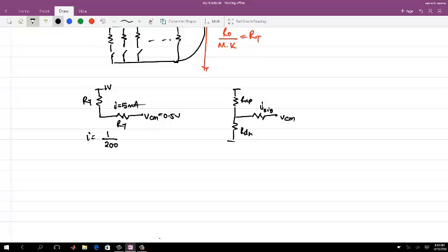When the output swing is lesser, the I signal is lesser, right? So you are having an I signal which is lesser than 5 milliampere, but the total current which you are taking from the supply is more. That's what we are seeing. So can you think of a way to lower the current which is coming from the supply?